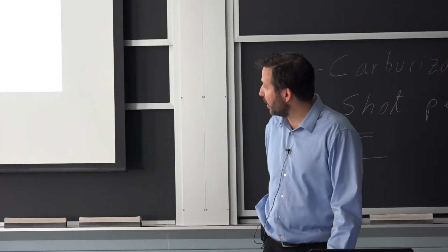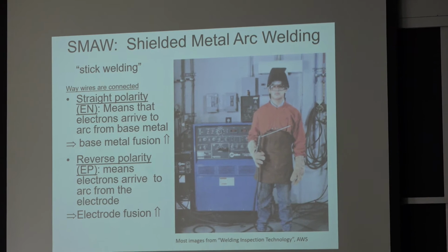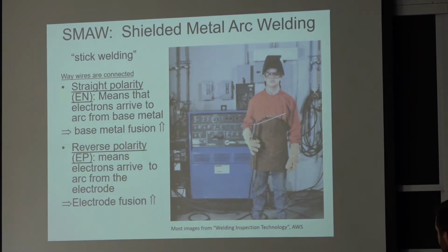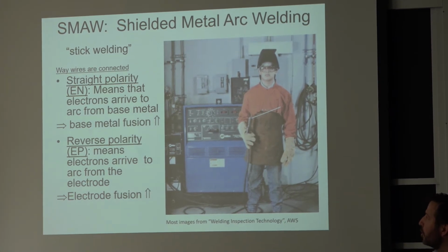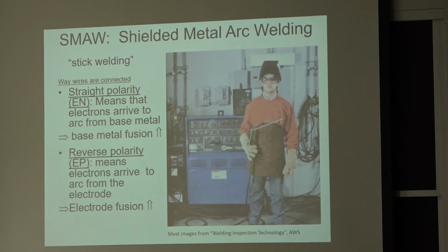So we'll start talking about welding. The basic process of arc welding has been around for a while, and it's very powerful because it's quick. If I take two parts, you almost need to try it to see, and they don't line up perfectly. There's a little bit of a gap. It's okay because you're going to come and melt a little bit of each part, and it solidifies quickly, and then all of a sudden you have a continuity in your materials.